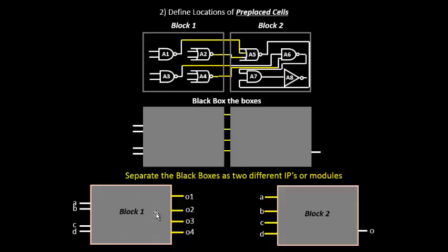You can give this particular block to some user, and that block to another user, and those two users will implement these blocks separately, and each will be implemented only once. Then these blocks can be connected in this fashion multiple times onto the netlist and used whenever required. So you do not implement this multiple times, you implement it once, and then it can be reused. This is the concept of reuse modules, where we have these small modules that can be reused separately on the top level, on the top netlist.